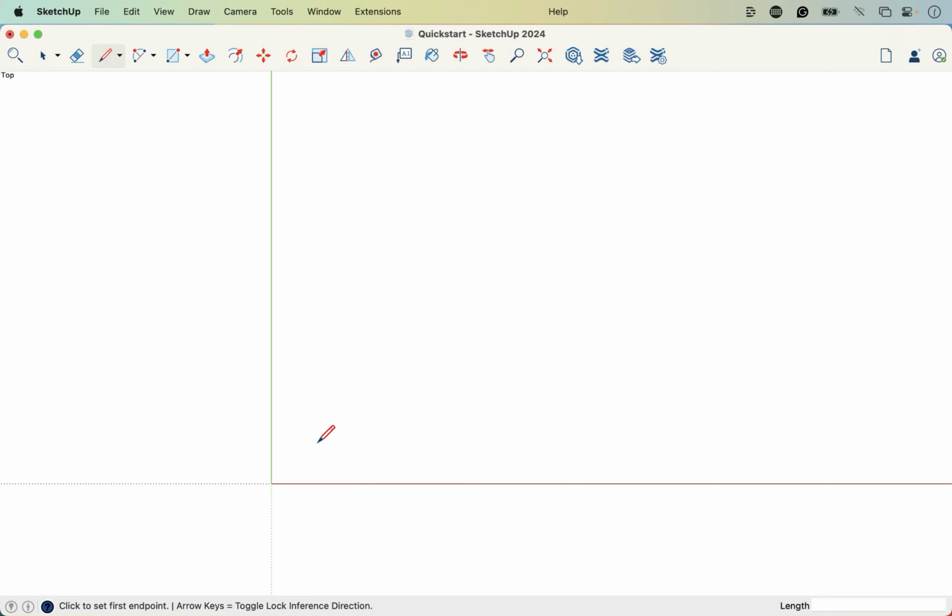And move to the right. So click, release somewhere here near the origin point, not on it, but just near it. Click, release, and then move your cursor to the right. Your line is going to turn red and it's attached to my pencil tip there.